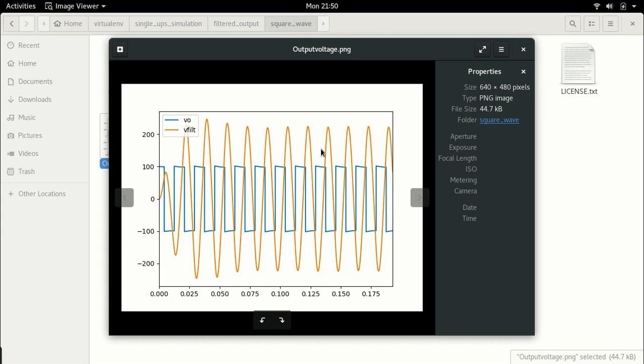And long back, if you were to notice, square wave modulators were either one, very bulky, or two, they would end up actually applying a square wave at the output. So the output would be a rectangular waveform, not a square waveform. So for these reasons, this modulation technique is now completely outdated. I don't think anyone uses this. It's always pulse width modulation, or there are other advanced forms of modulation.